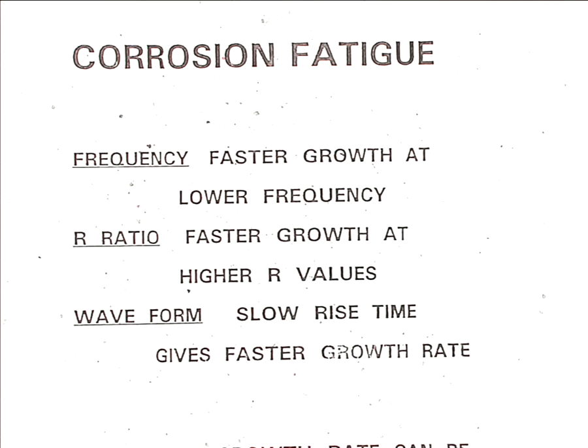But you can't do it for corrosion fatigue, because in the solution, the crack is opening and closing. And the amount of solution going into the crack and the ejection of the solution as it closes has an effect on the corrosion rate. So you can't do it fast, you don't get the same fluid dynamics.